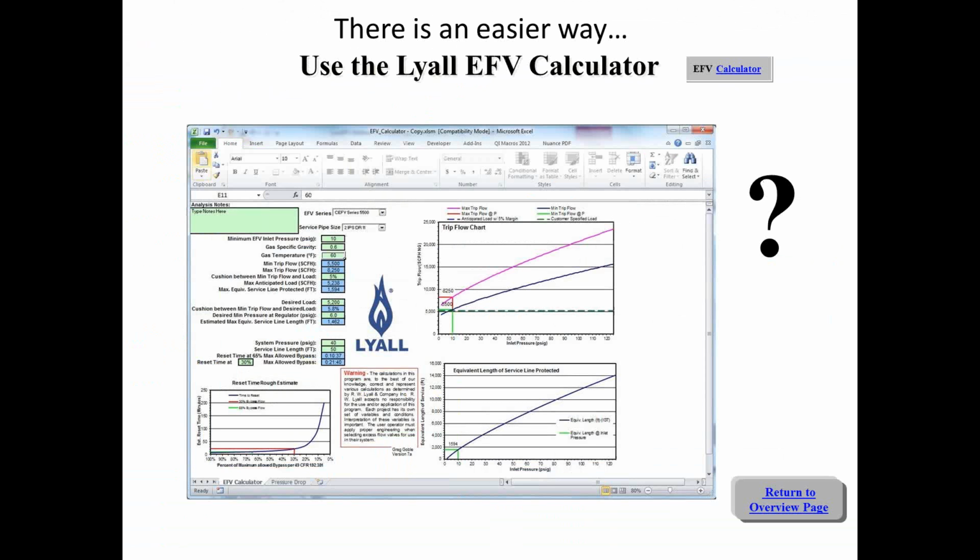And then, of course, you could put another excess flow valve on each branch, meaning the excess flow valves would be in series to protect that particular structure, or the service up to that particular structure. There's nothing that would prevent you from doing that, but you would obviously have to take care in the sizing of each section of that service to make sure that all the same considerations that we talked about here today are being met. I don't know if that answers the question.